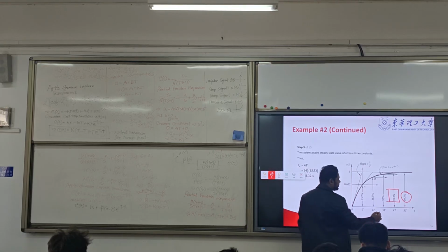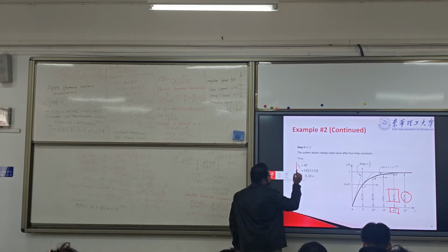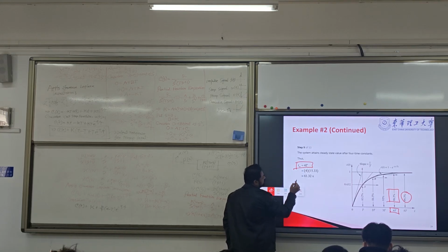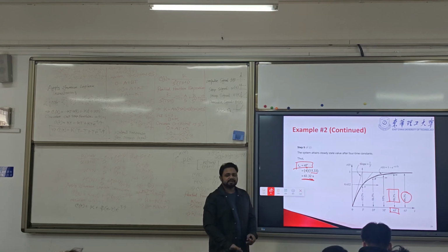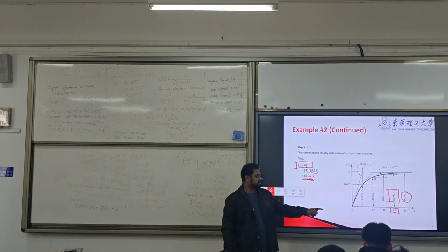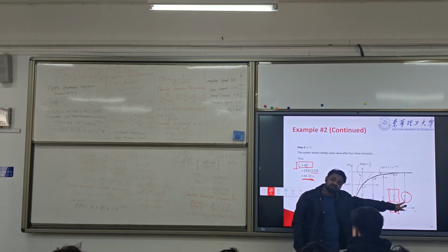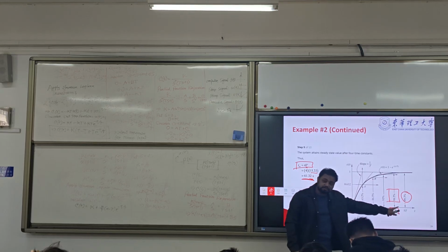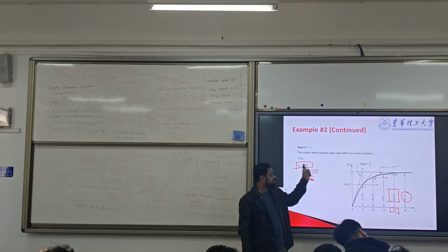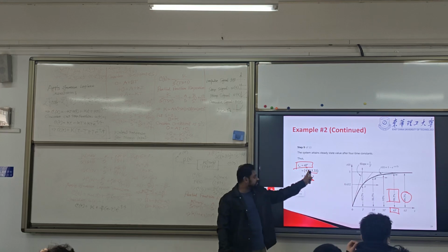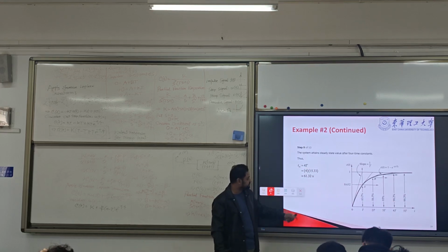So that is 4T. So this t is equal to 4T, and T we already know, the time constant, 15.33. That is your t, because it depends on which output you need. 98%, 99%. If it tells 99%, then you must multiply with 5T. But it is 98, so you must multiply with 4T.